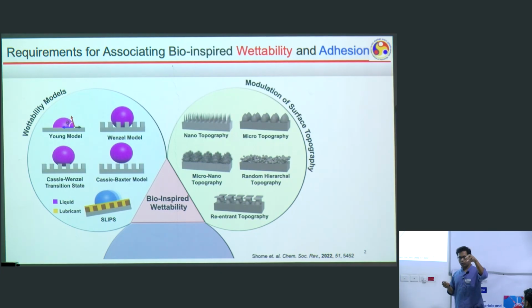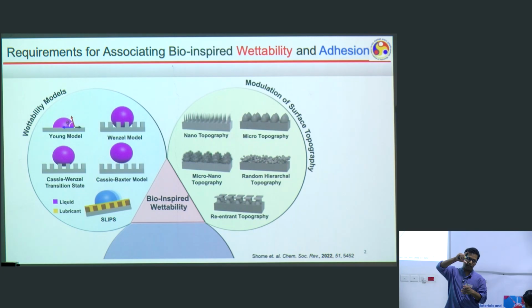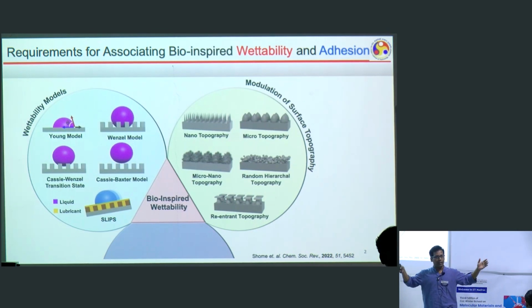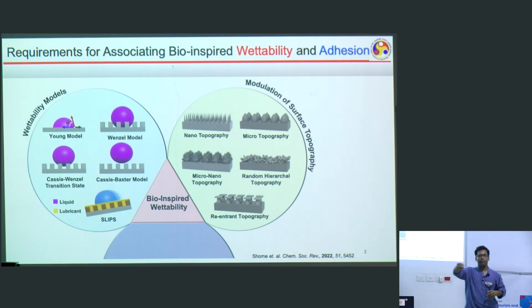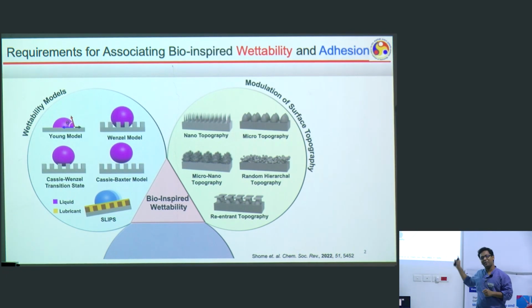Okay. Now, when you put the water droplet on a glass substrate, initially it will have a high contact angle, which in layman's language means more height of the droplet for a given size, and over time you will see that it's getting depleted, and then it will be stationary. After that, if you keep monitoring, you will see that the height is depleting while the contact line remains fixed. Why? Because most of the evaporation happens from the edges, and because of that you see the coffee ring effect, and that is the biggest problem when you look at self-assembly and all. I'll try to touch upon this concept at the end of my slides.